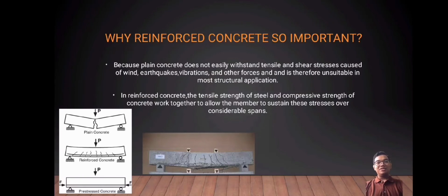Reinforced concrete is so important because plain concrete cannot easily withstand tension and shear stress caused by wind, vibration and other forces, and this is why it is suitable in most structural applications. In reinforced concrete, the tensile strength of steel and the compressive strength of concrete work together to allow the member to sustain the stress over considerable span.